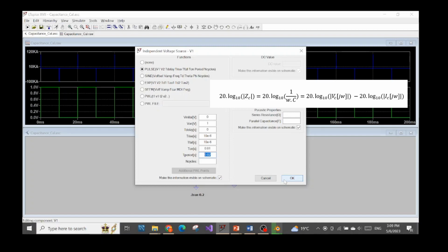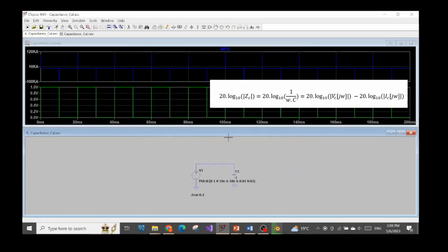That's why we can easily choose the frequency where we want to measure our voltage in the frequency domain: 50 Hz. And also at 50 Hz we need to get the measurement of the current in the frequency domain. And from those two pieces of information at 50 Hz, together with this formula, we will calculate, or derive, our capacitance.